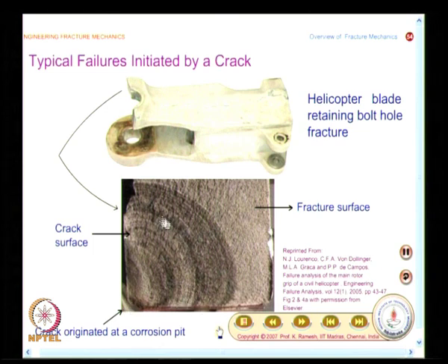So, this corner crack could be modeled as a quarter of an ellipse, and in fact, we would do this in all our analytical development. We would take a semi elliptical crack or an elliptical flaw inside. These are all easy to handle mathematically. The flaw can be modeled in this fashion for analytical development, more or less it will match with the nature of the flaw.